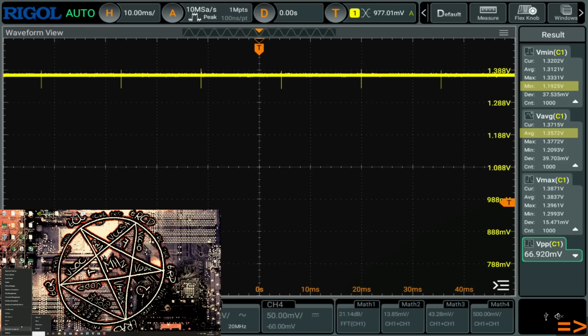There's some argument to be made for having an LLC setting with no V-droop, because if you're doing thermal testing or something, you don't want your voltage moving around. There are scientific applications for not having V-droop. There are no real world practical applications for not having V-droop. If you want to test heat sinks or water blocks, you don't want your voltage moving around based on V-droop, right?